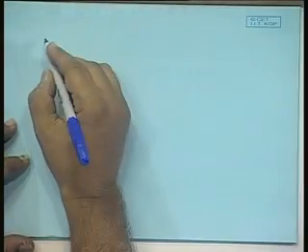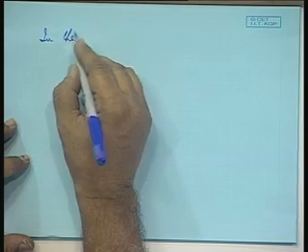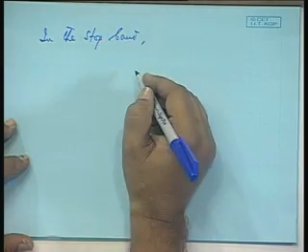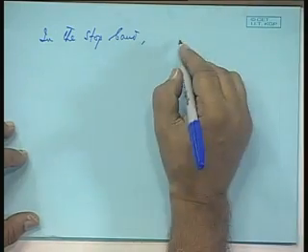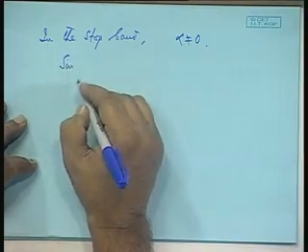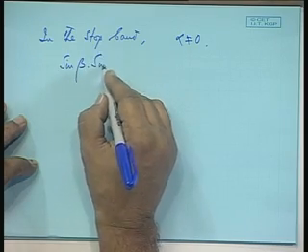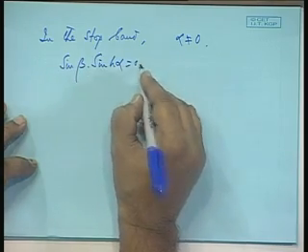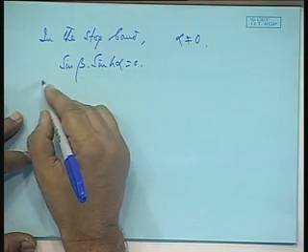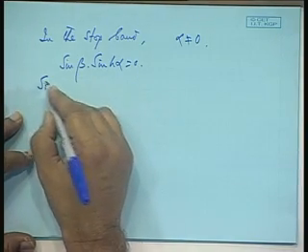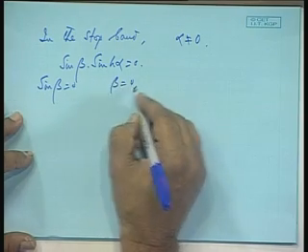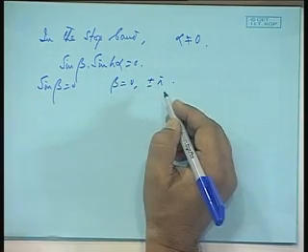Okay. Now, in the stop band, where alpha is not equal to 0, we put the other condition sin beta sin hyperbolic alpha equal to 0. That means there are two possibilities. If sin beta equal to 0, then beta can be either 0 or plus minus pi.